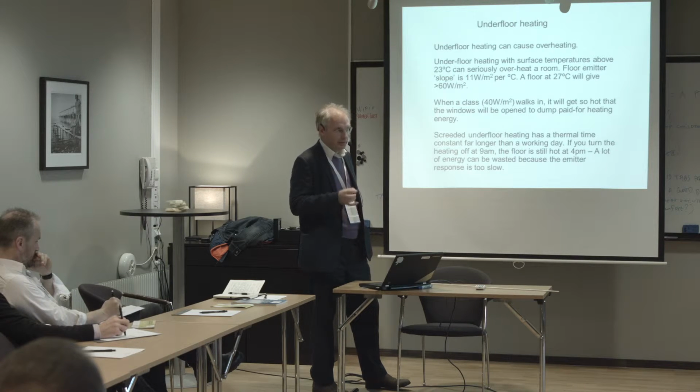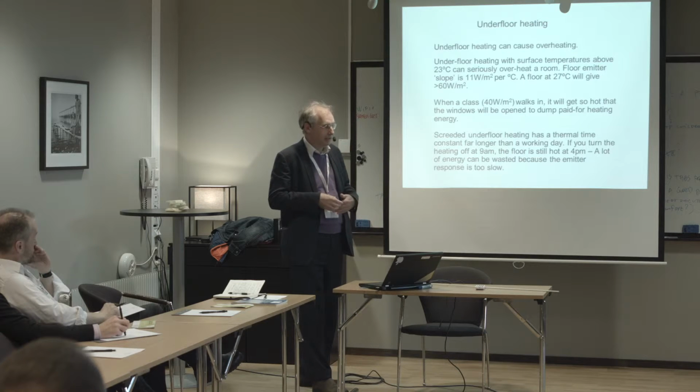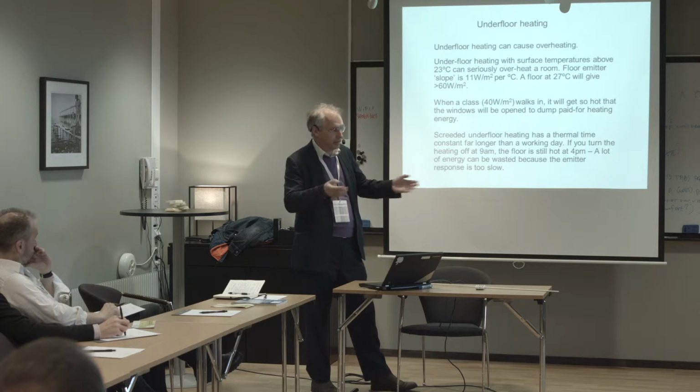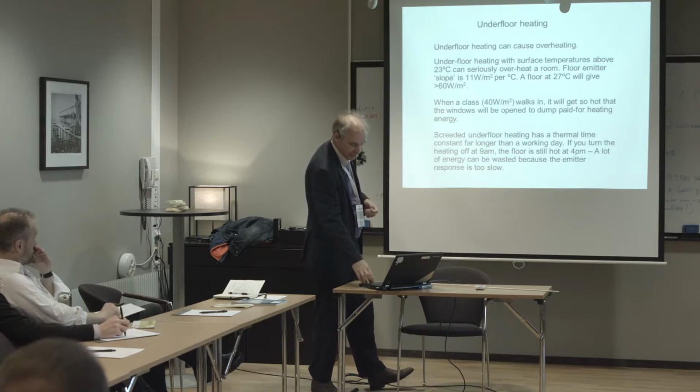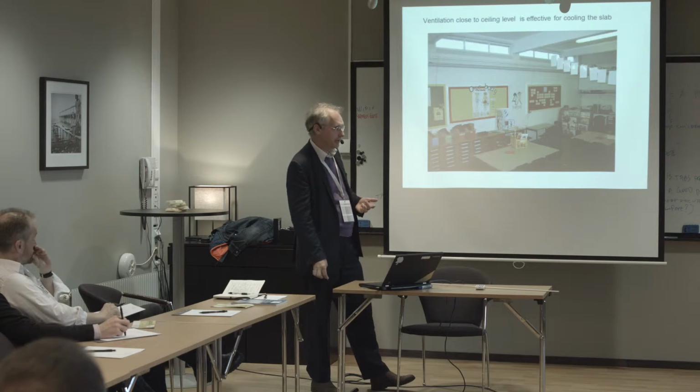topped up. But you do need an alternative heating system for the cold times, because people open the doors to outside. You know, primary nursery age children are in and out all the time, the door's open. So you need a very fast response, and that's where the metallic radiant panels are quite useful for nurseries. There we've got a problem with asymmetric temperature difference criteria.